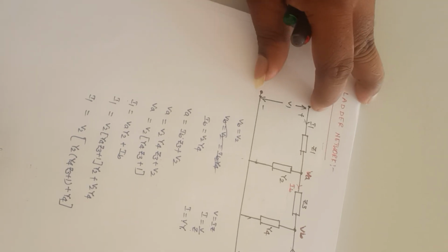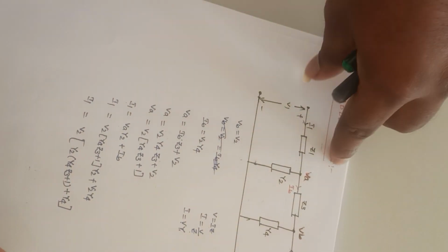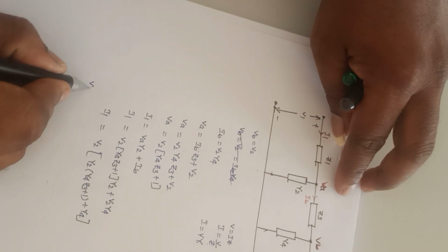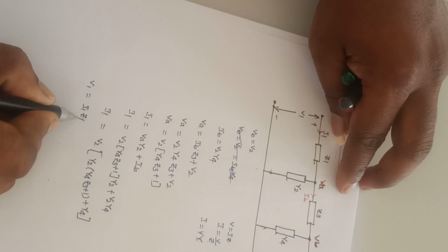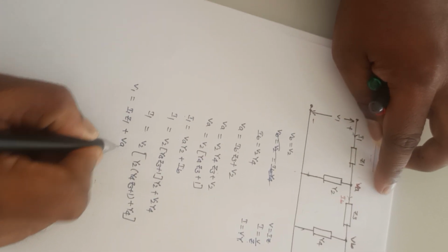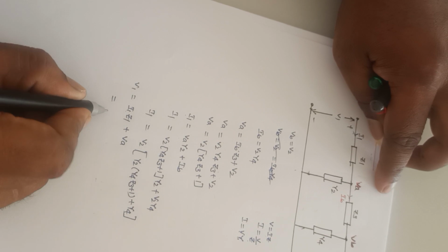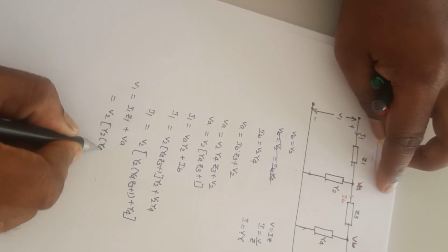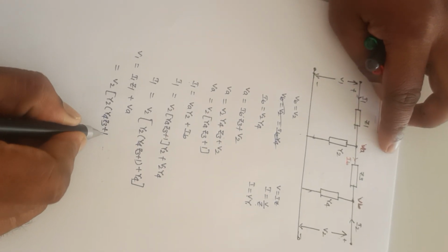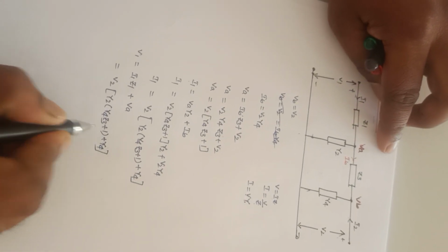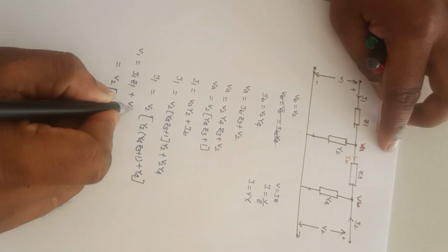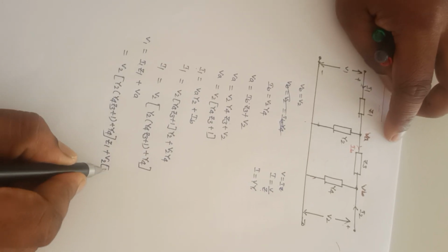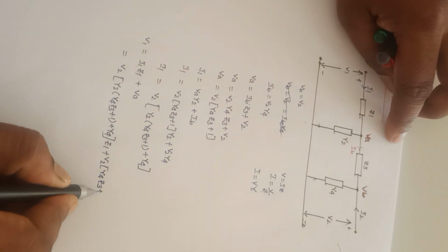Now the voltage V1 is equal to this voltage plus this voltage. So V1 is equal to I1 into Z1 plus VA. So I1 value is V2 into Y2 into Y4 Z3 plus 1, plus Y4, into Z1, plus VA, which is V2 into Y4 Z3 plus 1.